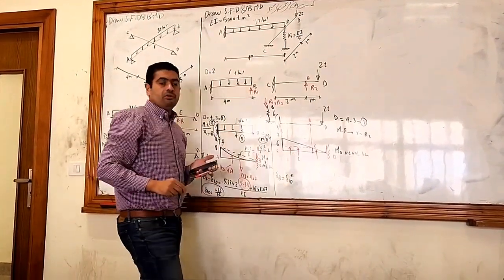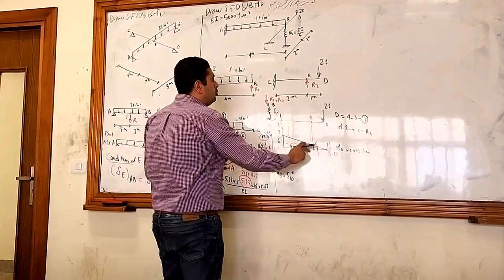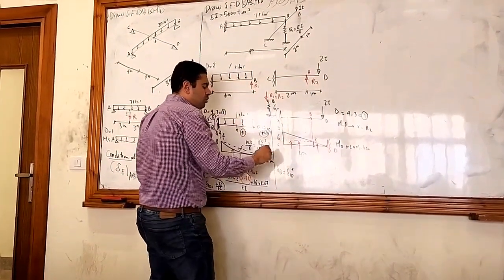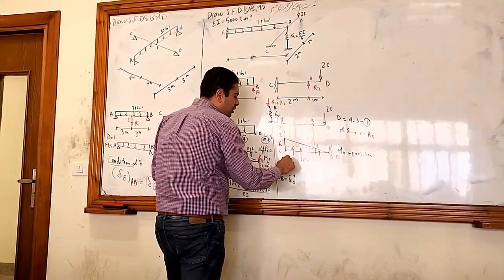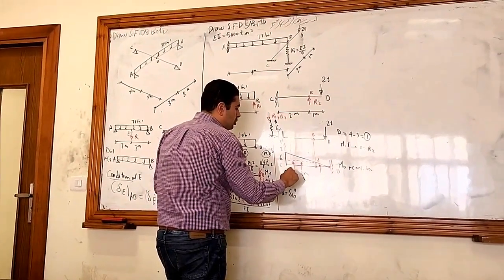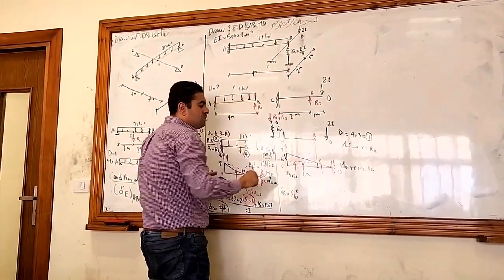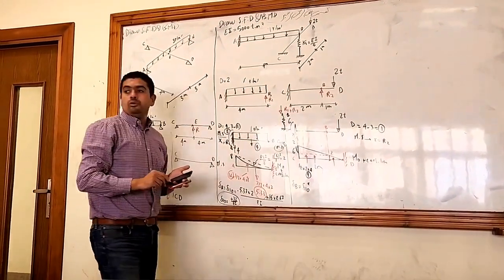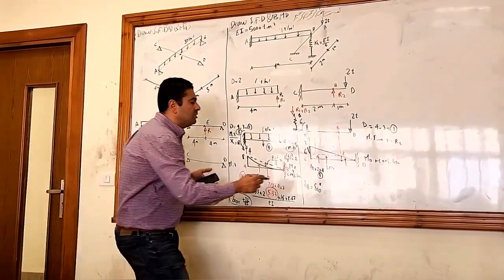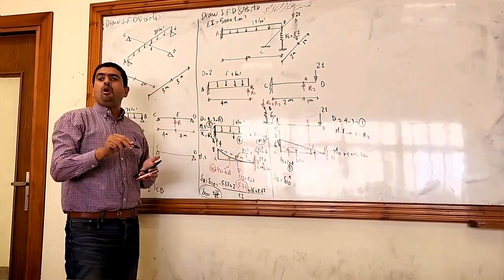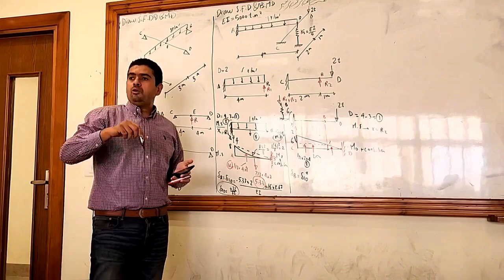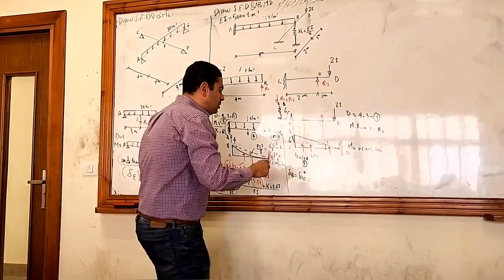It's for the rectangle. So it's 2 times 2, 4. And here is for the triangle half. The base is 2. And the height is the difference between 6 and 2, which is 4. So it will be also 4. Okay. So let's calculate the moment here. Both forces have a positive sign. Both of them, the tail of the arrow will be down.